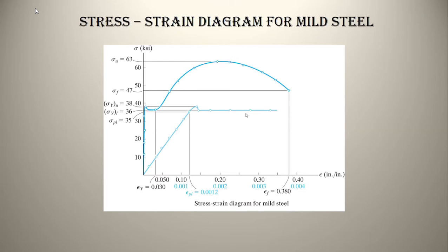Everybody good? So I would say that you really draw a line parallel like this to the original straight line, and wherever it cuts, that's the point of yield strength. That's the yield strength you read off. In this case, it is not varying, it's the same here as well as there, but the definition is 0.2%.